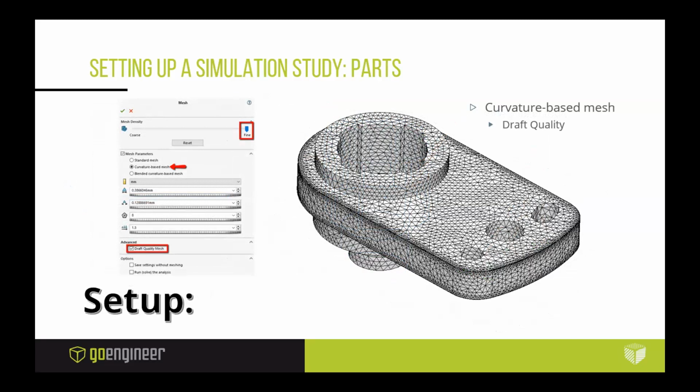And for those of you that are new to simulation software, think of the mesh as a way to sample what the geometry is. If I set everything up in simulation and then hit run without meshing it, the software can't see the actual model. The mesh is how it feels what the geometry is. So the more mesh elements and more calculation nodes in it, the more detail it can feel when it runs a study. So it knows exactly what the geometry looks like. I explain it that way because the more detail you add, the more you can feel, right? But if you add more resolution, at a certain point you can't really feel any more detail. And that's a similar idea with a solver. You can add more calculation nodes, but more calculation nodes doesn't necessarily mean more accurate, up to a certain point. So you have to find that sweet spot when you're playing with these tools.